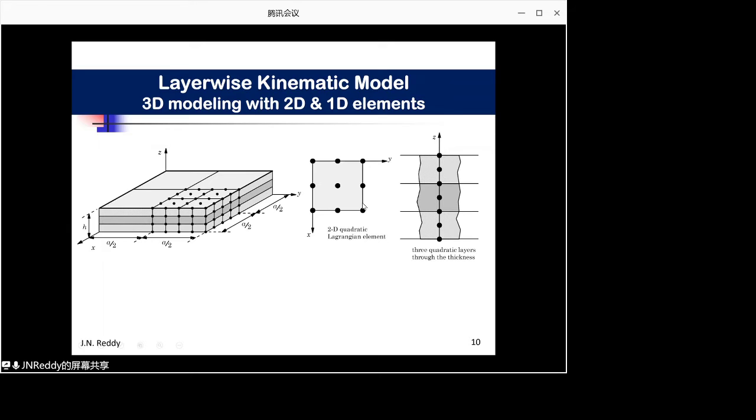So I'm showing you the results of sigma XX. This is a thick plate. Through thickness, 0 at the bottom, 0 at the top, the middle layer is 90 degrees. 0 degree means the fiber is taking the load. So you can see the stress in the fiber is going to vary according to this equation as predicted by exact 3D elasticity. Same in the bottom layer.